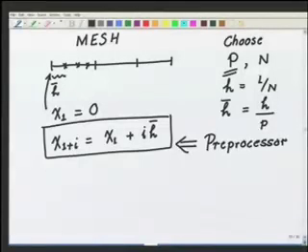What other information we should create here? So after making the mesh, we should also give the element information, that is, in the element K, which are the nodes? These nodes that we have created, these points. They are important because we would like to know the extremities of the element, as well as we need these points to construct the shape functions.